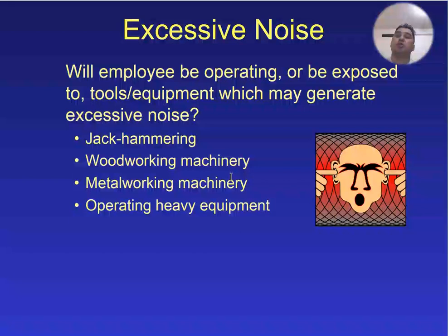You have to make sure that as per the OSHA standard, they are not working more than 8 hours continuously if the noise is more than 85 decibels. So you have to check: if the dB is going high, then the working hours will go down. As per that requirement, you have to take the steps.